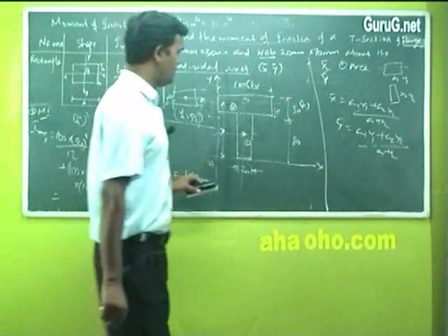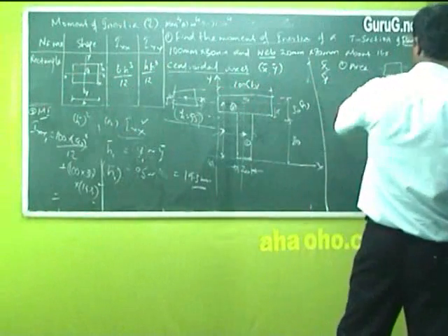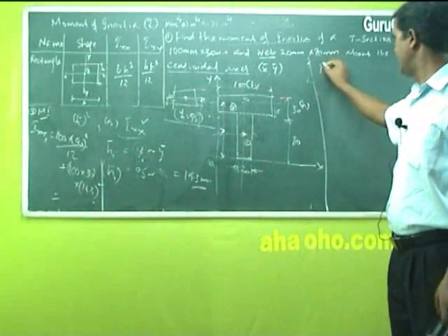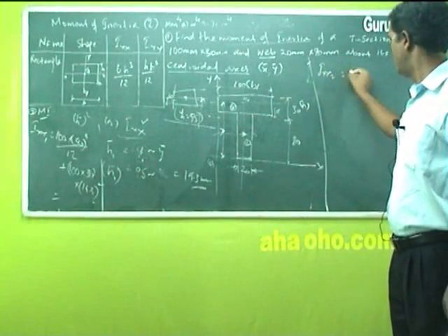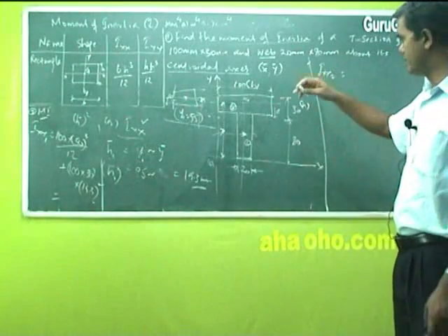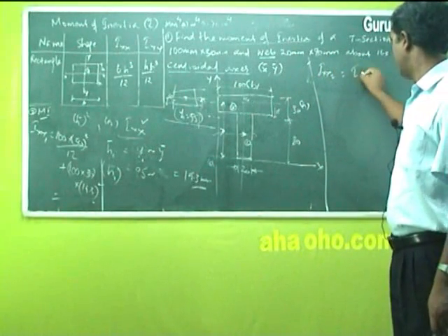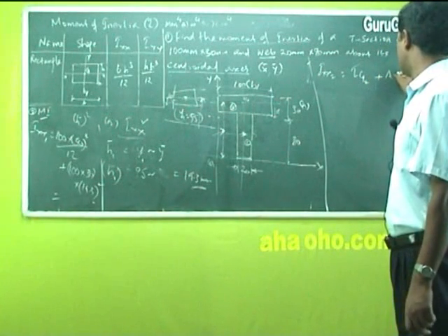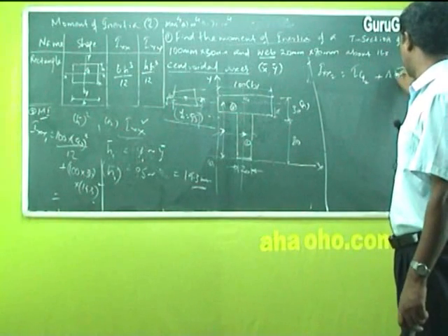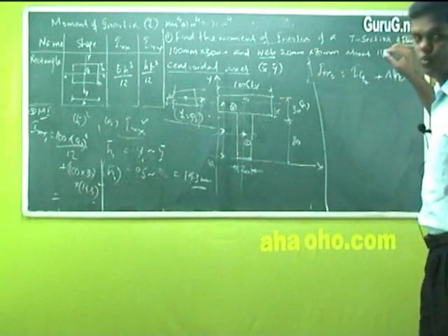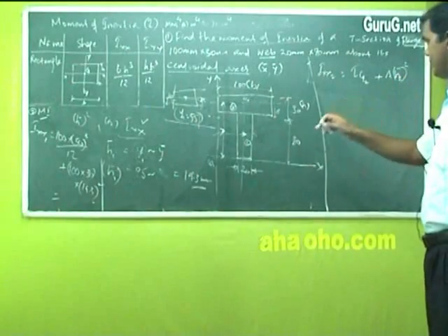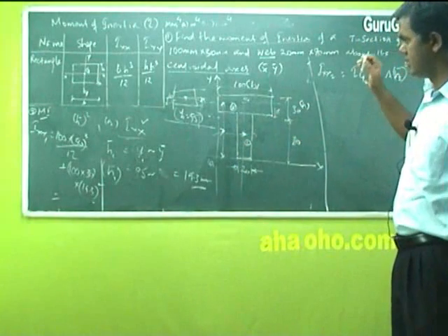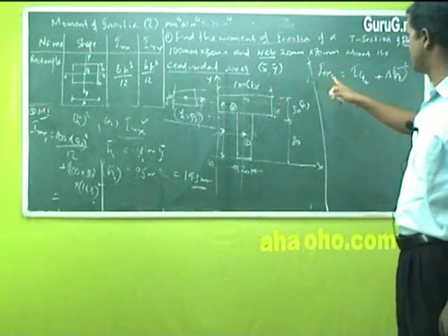Right. Now I'll just erase this. Continue with this here. Now IXX2. What is IXX2? The formula is again your IG, center of gravity for 2, plus area into H bar square again. H bar means H2. Again repeat for this sketch, for IXX1 and IXX2 here.